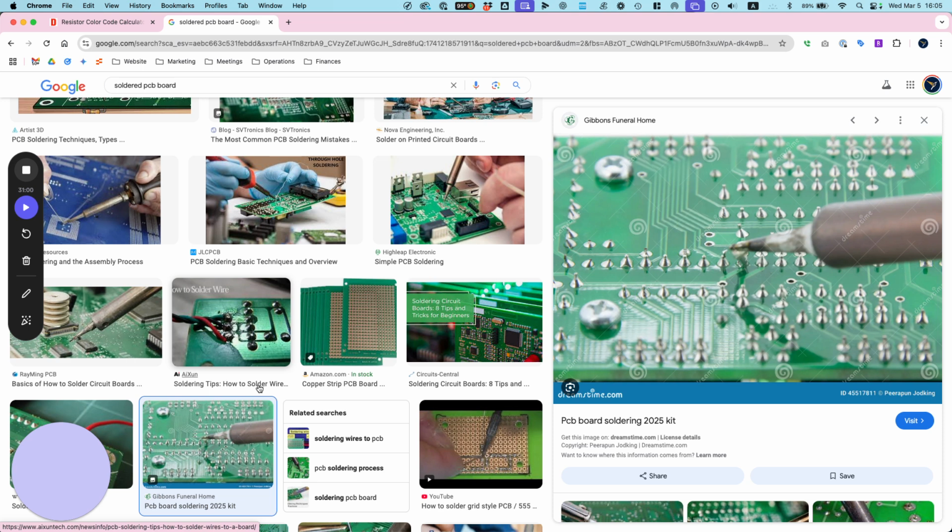3.7. It should more or less be that, but let's just verify. 3.7, is that a coincidence? That is the voltage of a LiPo cell. That's at least the baseline voltage, okay? What I mean by baseline voltage is that in reality, when you charge the thing up, it's actually going to go up to like 4.2 volts.